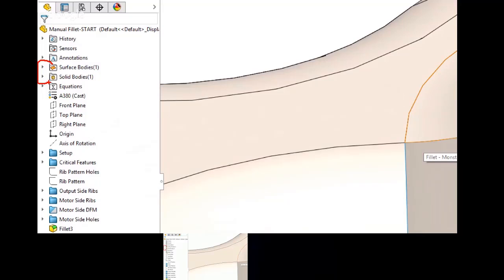So if you use one of the other two delete commands, it would retain the solid body and there would be no surface bodies? If it were possible to patch it, yes. In this case, what would have happened is it would have deleted that face and patched it up with one that was pretty much similar. Can you show us? Yeah, let me come back to that though.